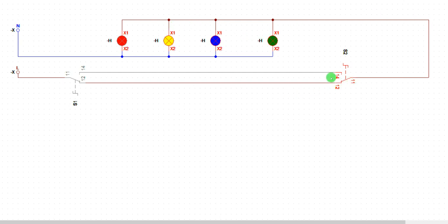It comes to the lamp. If I want to shut it down, I shut down. Then trace your continuity. From here, supply comes here, goes through, comes here and it is open. This one has closed to the other side. So that is why it's off. Okay, that is continuity. That is the way you do your two-way control.